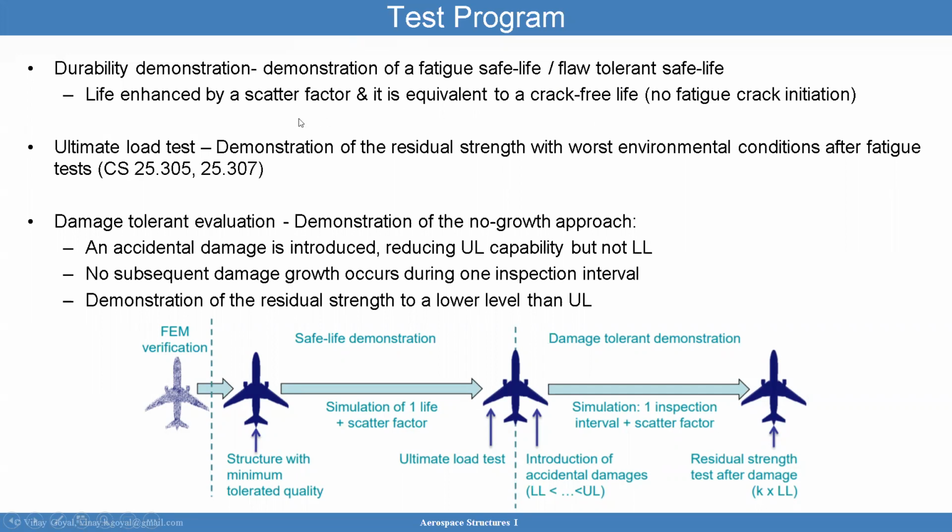And so in this case, you have the test right here. You want to make sure that your finite elements verify that structure. And you want to come up with a structure that has a minimum quality. Whatever quality you're going to allow, you want the minimum quality they're going to allow, and that's what you want to manufacture here. And so in this test, what you're really looking at is ensuring that you do a safe life demonstration. Now, this safe life demonstration is going to be a pristine one.